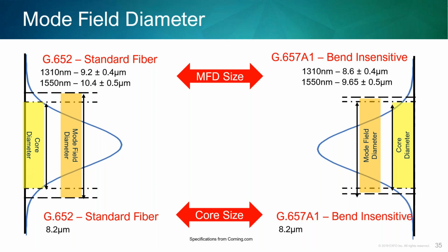Where do we see this transition the most? Going from the office to the outside plant, and going from the outside plant to the CPE location. We see that, right? Drops can be ordered as bend insensitive. Fibers that run from, say, a modular pre-terminated FDP that has that tail that goes out to the field and splices at the outside plant bolt: inside the building, it's bend insensitive. Outside in the outside plant, it's not.